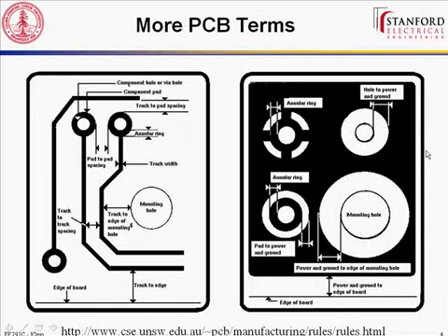Question? Are mils standard units, or does it vary from manufacturer, whether you're in imperial or metric? So a mil is a standard unit for PC board fab. Some companies will go in millimeters, so it just depends. But basically everything that we're going to do will be in mils, and if you have metric parts, you'll have to convert them to mils. But mils and millimeters are the two different standards, which unfortunately sound a whole lot alike. But they're very different. If you have a millimeter component and you accidentally interpret it as mils, it will not fit every time.